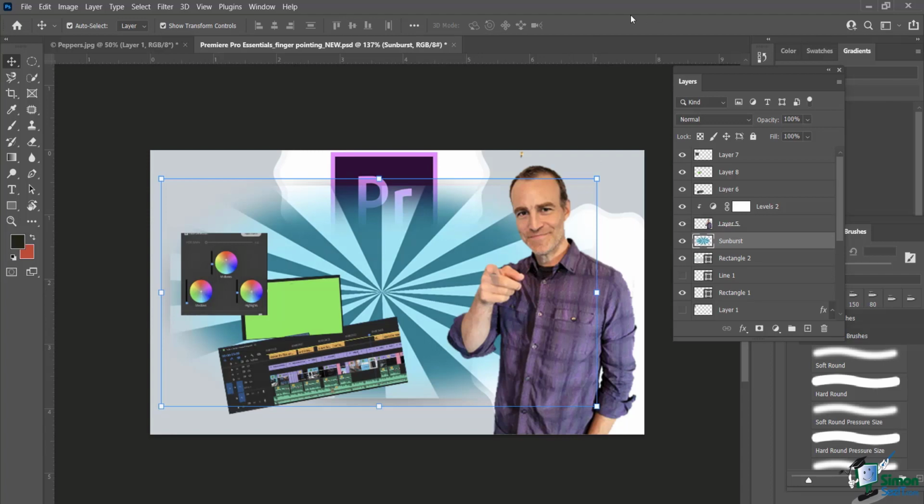All right, but just really take in and integrate what we just did here. Okay, so we worked with duplicating layers in a number of different ways. Okay, and as a result, right, we were able to have a lot of different options of what we were going to do, right? Using the keyboard shortcut, right-clicking, using other keyboard shortcuts like the Alt key, Control or Command J. All right, and then when we duplicated it using the dialog box, we were able to rename it and also place it where we wanted to go.